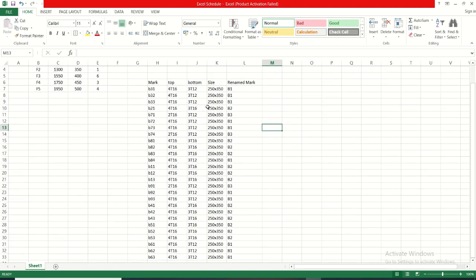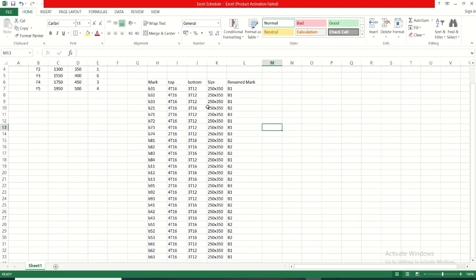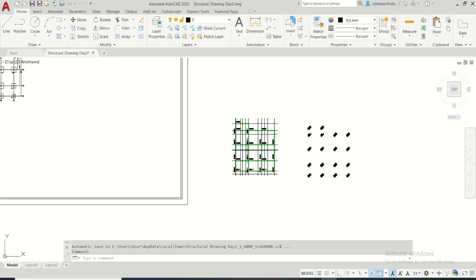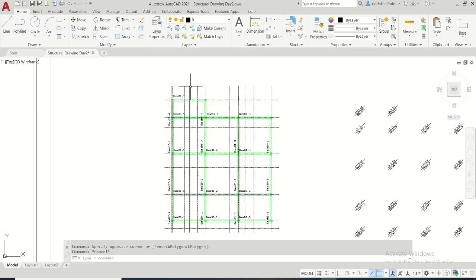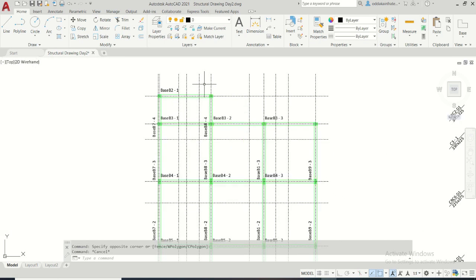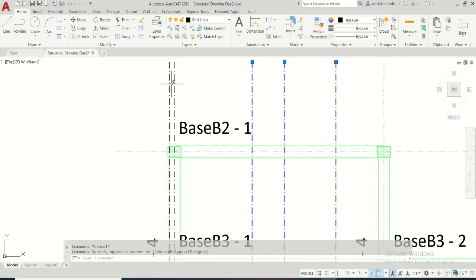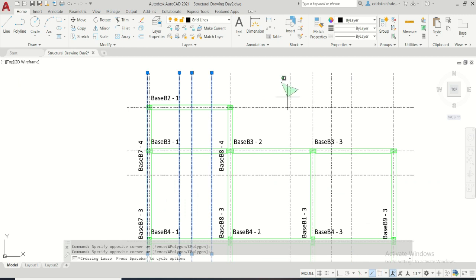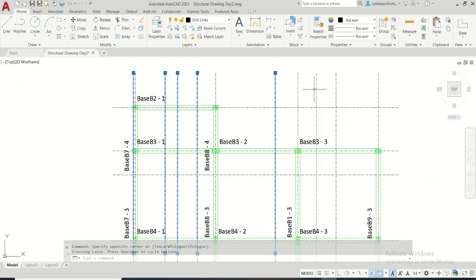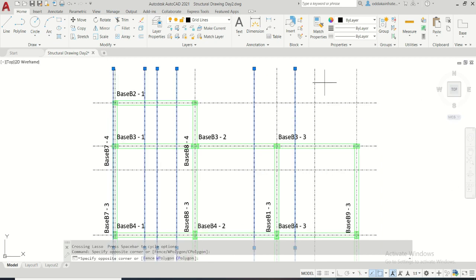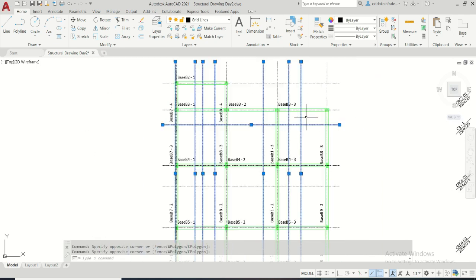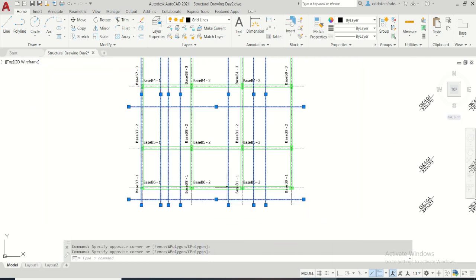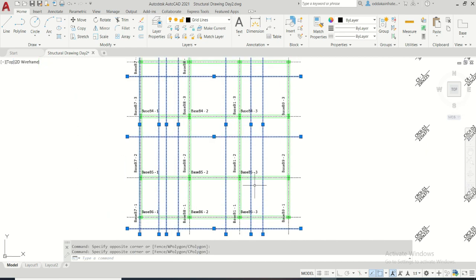Now what we are going to do is name them, and we're also going to create the schedules here. For the schedule, we have already done a similar thing in the CAD part. But first of all, we'll delete all the particular center lines which we don't need, so that they don't create any unnecessary space. So select it, and from here I think this one, and this one also. So all this selected, delete.